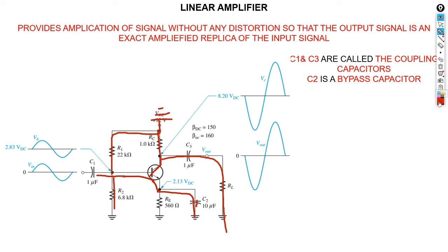But if we have to do DC analysis, what will happen if a DC current is coming? This current cannot flow there because it's open. This current can only flow here. When it goes there, it cannot flow because it's open. This current will go like this, and then this current will go down, and then will come like this. This current cannot flow there because it's open. Can you see? So we are doing DC to bias, AC is to flow our signal into our capacitor.